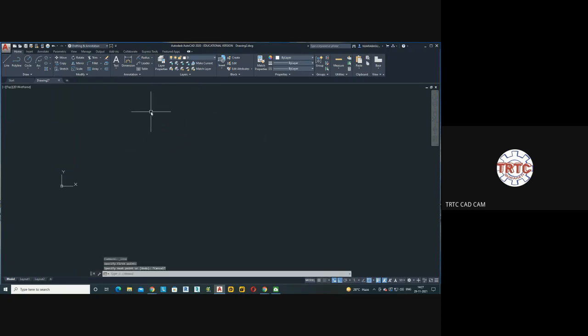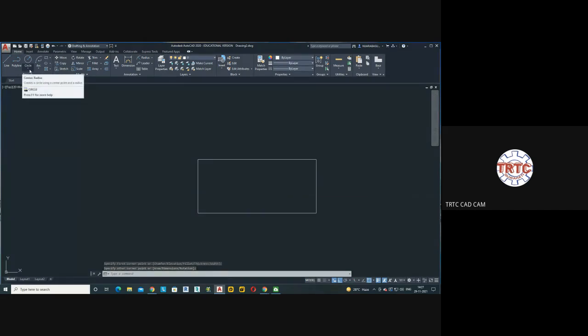So let's say I have a drawing here. But by mistake I need to draw a circle at the middle section, and I have mistakenly drawn the circle here. Now I have to draw the circle exactly at the middle position of this line. One option is to go for circle, take the mouse over this line, and it will give me this midpoint. Click on the midpoint, enter the value of the radius, and it will give me the circle. But can I move this existing circle to that position?